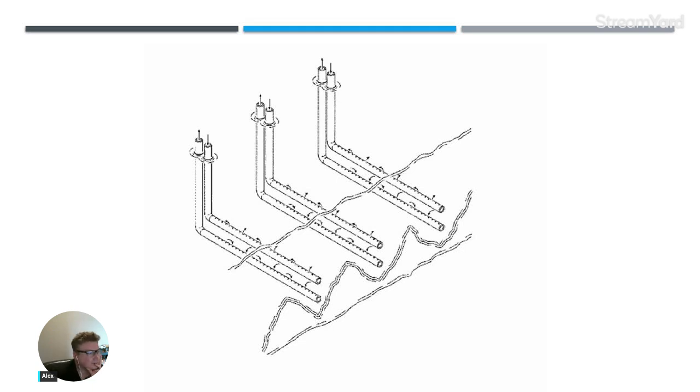So then what happens after 5, 7, 8, 9, 10 years? I inject steam, but because I developed most of the stuff that's near the wellbore and towards the height of the chamber and expanded this laterally, now I need to inject much more steam. But how much oil do I get in return? More or less? Less, right?